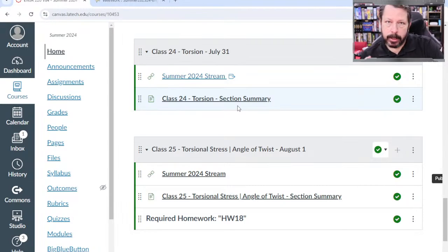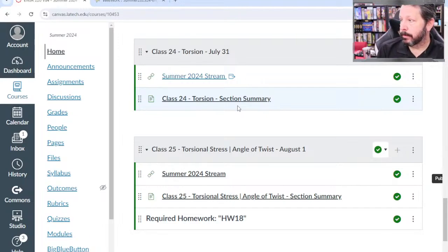So we worked through a couple of problems on torsional shear stress and torque in the different sections of a shaft. And today we're going to add on to that the idea of angle of twist. One way things could fail is they have too much torsional shear stress and exceed your limit, maybe set for yielding stress, not to exceed some number. These are shear stresses, so the yielding shear stress, or maybe a fracture strength. But it could be that the shaft just twists too much, and that's considered failure. So today, that's what we're going to look at.